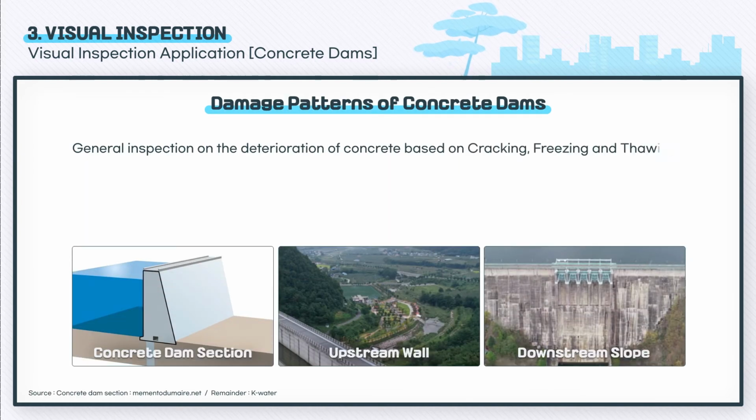For concrete dams, there is a need to conduct a general inspection on the deterioration of concrete based on cracking, as well as freezing and thawing, alkali aggregate reaction, and so on.